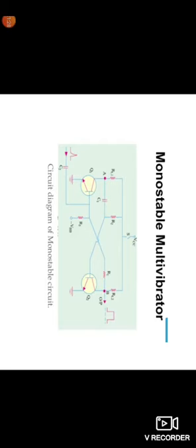Here the external triggering circuit R3 minus VBB is connected, and C2 is connected, and the two transistors are represented with Q1 and Q2. These are cross coupled transistors. There is a point A near Q1, across the collector terminal of Q1, and there is a node point B across the collector terminal of the transistor Q2. The output is taken across the point B, that is a single pulse.